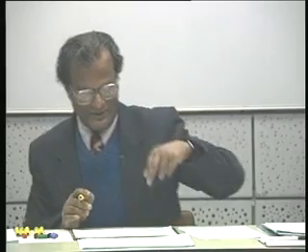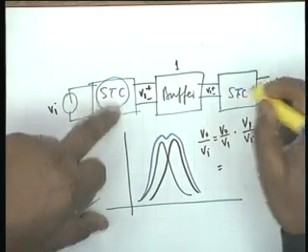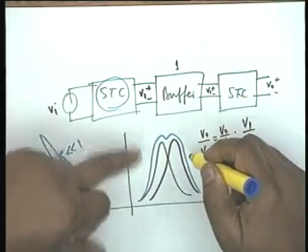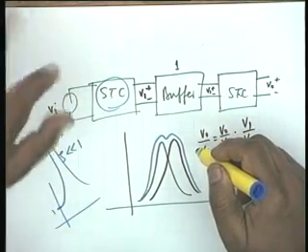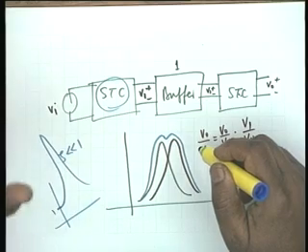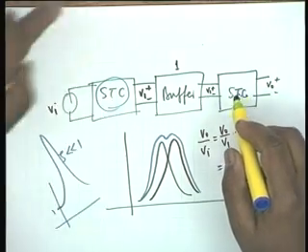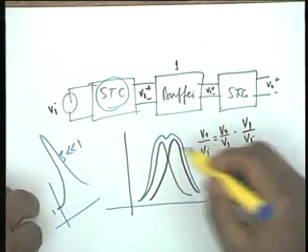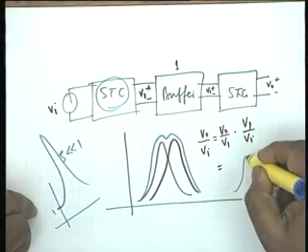Alright. What I am talking about is two single tuned circuits being coupled and decoupled like this. They will produce a response which is similar to the response of a double tuned circuit. Alright, now what is your question? These are not double tuned circuits. If both of them are double tuned circuits with slightly different tuned frequencies, yes, that's right, then I shall have a response like this.